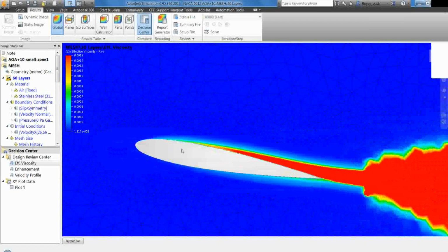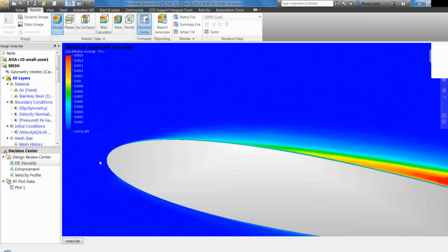Okay. But when we start coming in and looking at our flow profile, you can really see how the development of our boundary layer kind of looks like that. Okay? So especially in this leading edge where you want to really capture the pressure coefficients going around the airfoil shape as well, you probably want your mesh enhancement to be about this thick.